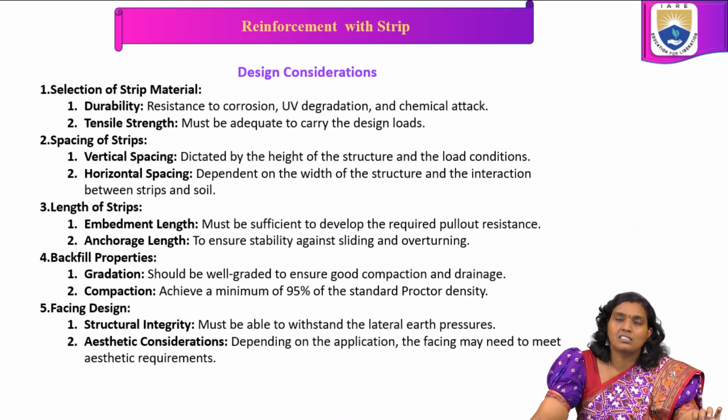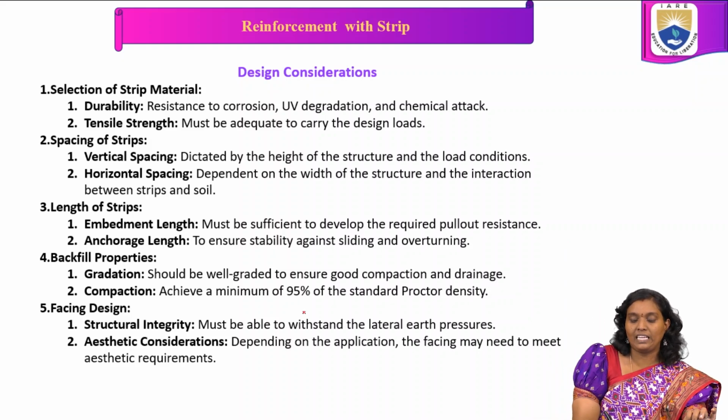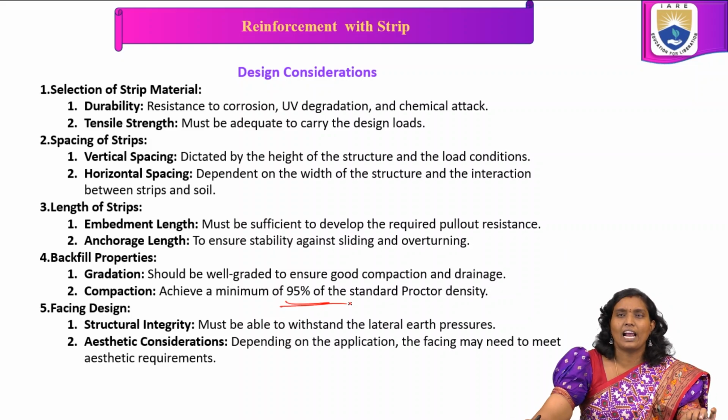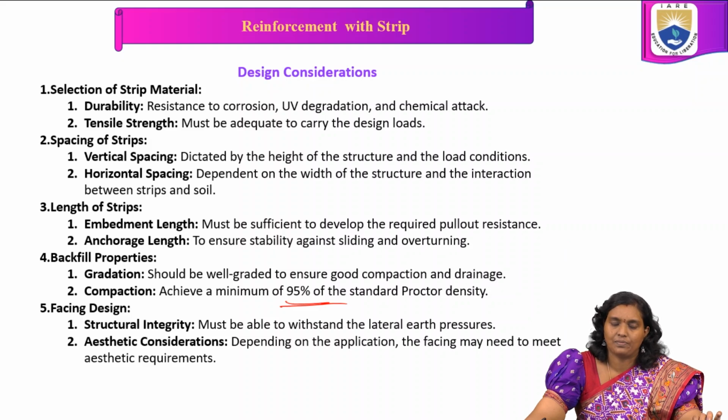Gradation should be well graded to ensure good compaction and drainage. In compaction, achieve a minimum of 95% of the standard Proctor density.